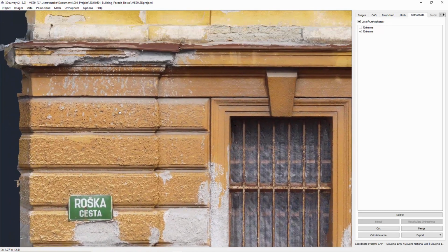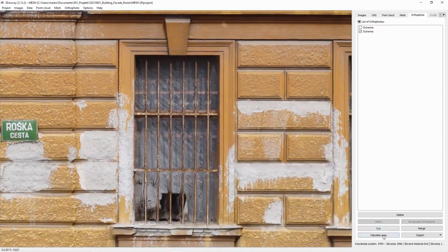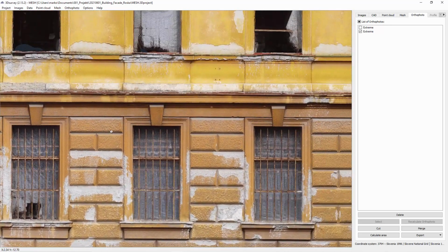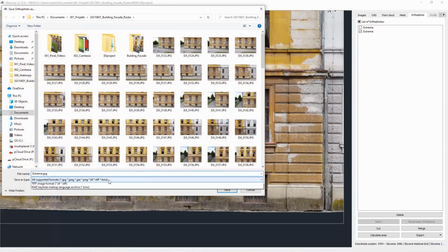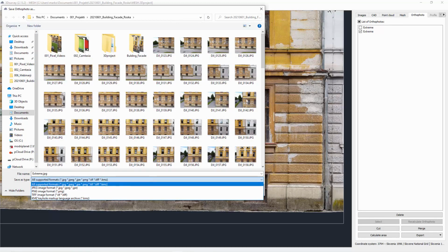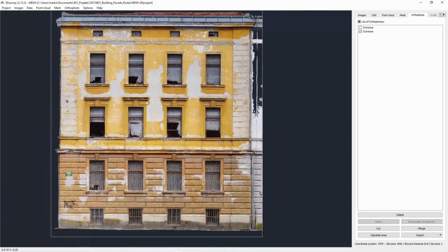It's really nicely visible, and in case we need to measure any distance here, for example, if we would like to calculate area from this specific window, we can easily click 4 points on the orthophoto and we have the area is 2.58 meters and so on. Or if you'd like to export this orthophoto as, let's say, a KMZ or JPEG or TIFF file to import it to AutoCAD or similar CAD software and draw out the CAD lines or anything like that, you could easily do it.